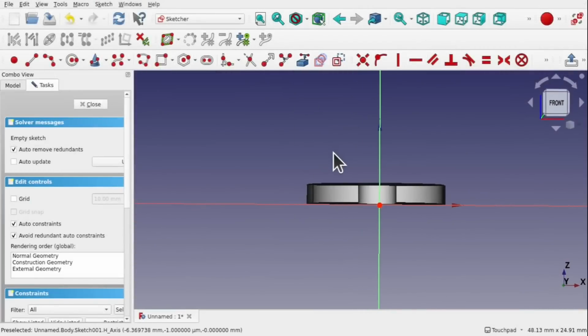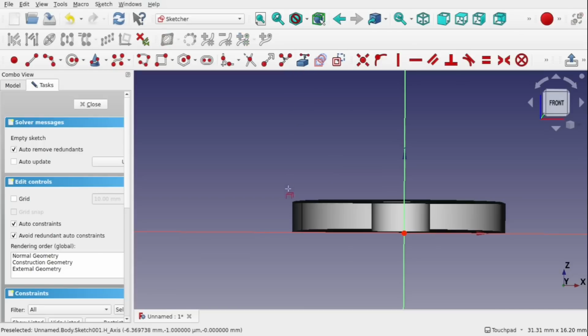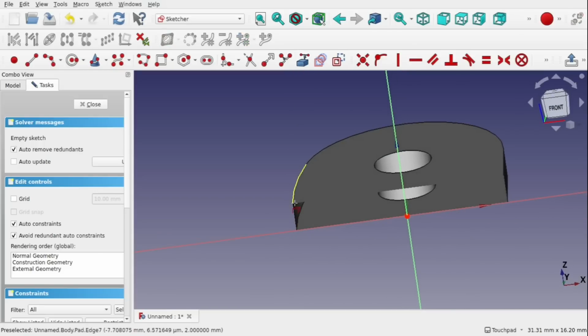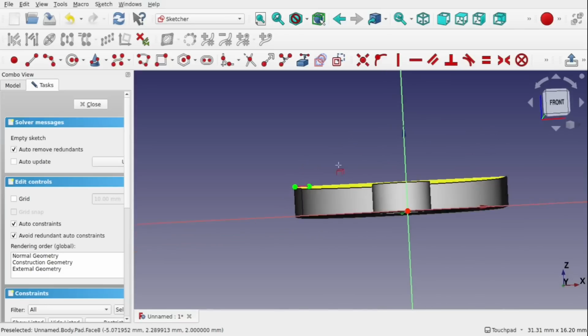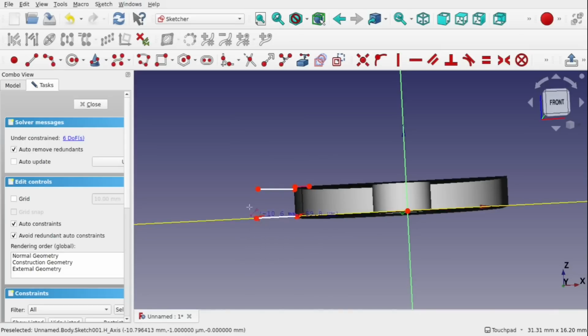So we're going to import some geometry, and we're going to come around and use this vertex here. Can't get the vertex, then we just bring in this arc. So we've got that point there. We don't need the bottom point because we can place it in line or actually attach it to this horizontal. I'm going to sketch a line coming out and do the same for down here, placing it point on object constraint along here, and we'll do the same for a line that goes down here.